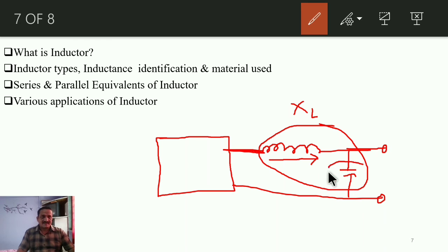Again over here a capacitor is present in parallel, so it will provide a bypass to those AC components like this. So those AC components will get grounded, while the capacitor stores the energy and does not pass the DC component, meaning across this capacitor there will be stored energy with the polarity like this. So the net output voltage will be purely DC, or the ripples, the AC components or harmonics, will be removed by using this LC filter.